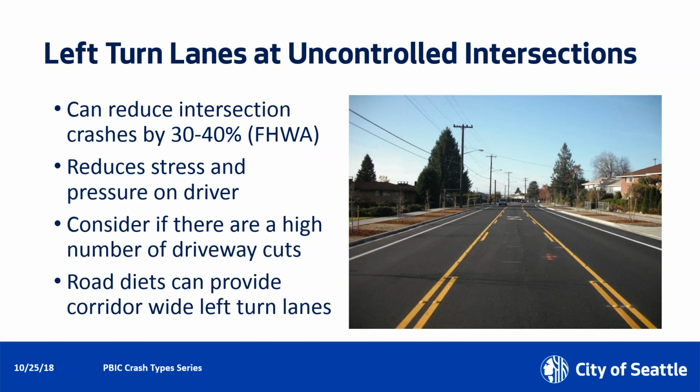Anecdotally, you would understand that this reduces the stress on a driver, reduces the pressure. In a situation where it's an active travel lane, they may feel pressured by vehicles behind them to make a quicker turn, in which case you're probably not looking for pedestrians as much, you're just looking for those gaps in vehicular traffic. Also really beneficial if there's a high number of driveway cuts, just because you're increasing your pedestrian exposure along the corridor.